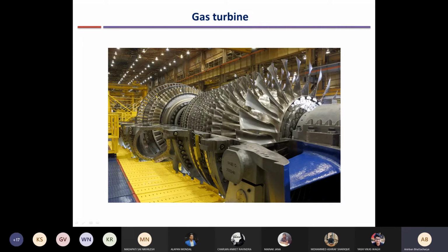Very, very dangerous thing. So they are designed very carefully so that the creep is very limited. So it is not that the melting temperature is a problem. Melting temperature is very high, 1900, 2000 degrees centigrade for nickel-based alloys. But creep limits the temperature to around 1200. Nowadays, modern aircraft with a lot of cooling and single crystal blades and directional solidification are limited to 1100, 1200 degrees centigrade.